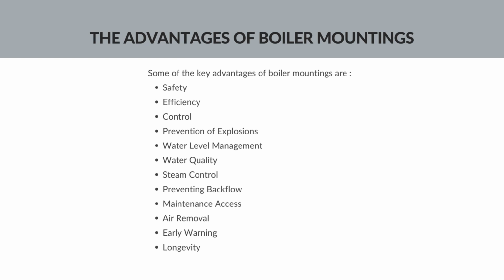Early warning. Fusible plugs act as early warning systems by melting and releasing steam when water levels are dangerously low, alerting operators to potential issues. Last is longevity. Properly functioning boiler mountings help extend the life of the boiler by preventing damage due to excessive pressure, low water level or poor water quality.